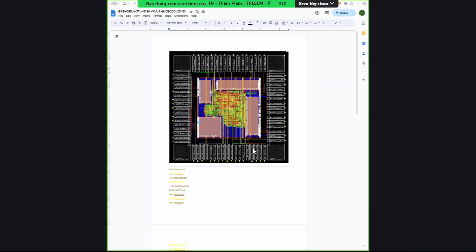So you make sure you optimize and add blockages, because you don't want to place cells on these tiny gaps anyway. Just zoom in on those areas and see if those tiny M1s are floating. Is anything connected to that M1? More likely there's none. Or your M1 might not be connected to the stripes, so check the vias to see if the M1s are via up or not.